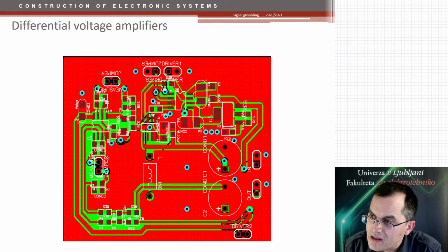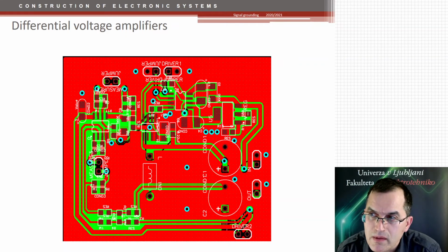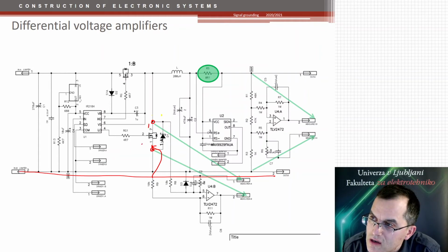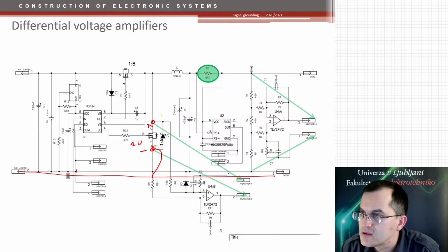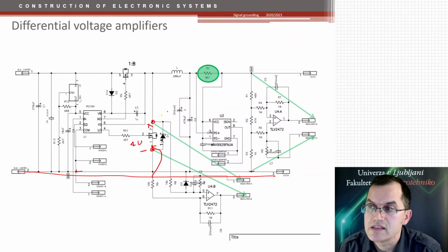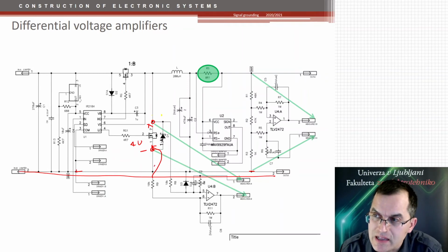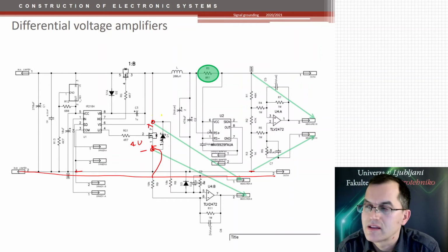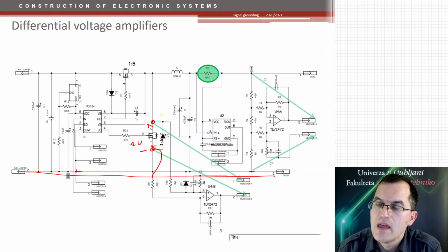So grounding it directly here would be a problem, because then you would measure something else. And since the voltage here is a few millivolts again, you can easily have a few tenths of millivolts of difference between different ground points if you measure it somewhere else. And that's quite a problem. And these are the cases where you want to do a single point connection to a point where you want to measure exactly that voltage and nothing else. For the rest, it's not a problem. The only problem is ground.